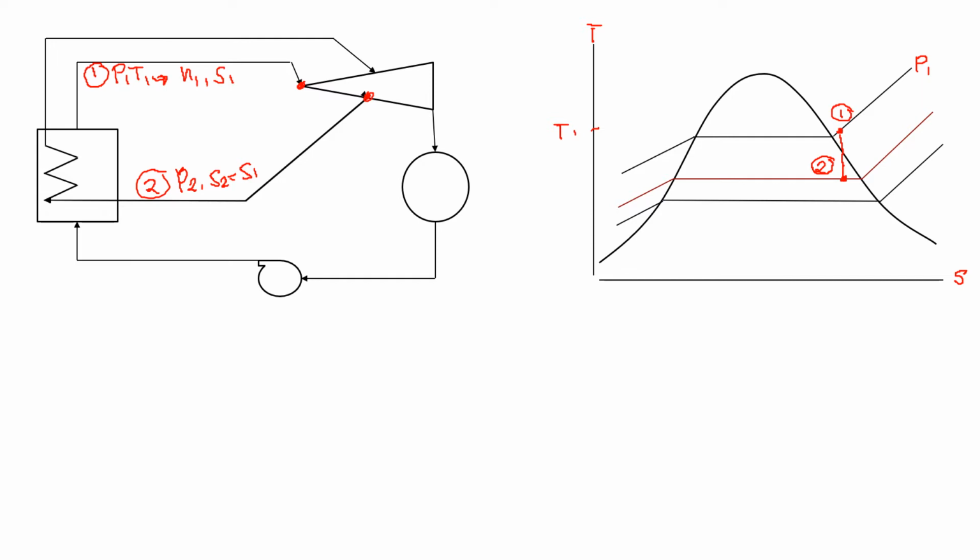So to utilize the pressure and gain more energy or work without compromising the safety of your turbine blades, we will reheat the steam in the steam generator.